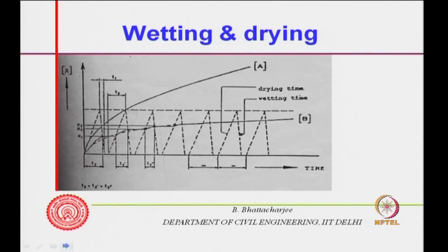So, then the carbonation front will progress in this manner. In the first cycle, you see, one can approximate the drying and wetting, because wetting is more or less instantaneous, then again drying and wetting, then there is a small gap, drying and wetting, small gap, drying and wetting. So, this is the conducive moisture condition during which carbonation will progress.